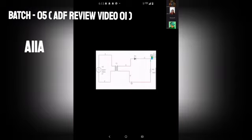This circuit is a simple half-wave rectifier that converts AC voltage into pulsating DC. The AC source provides 100 volts, 50 Hz to the primary side of the transformer, which then delivers a suitable AC voltage at its secondary winding. This AC from the secondary goes to the diode D1, which works like a one-way gate.